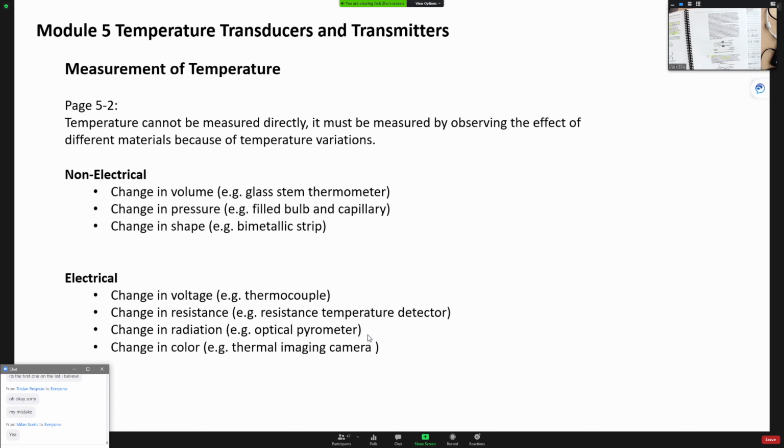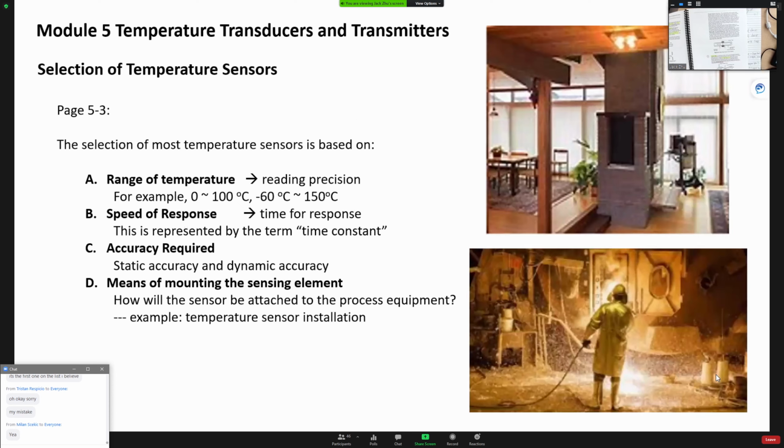The regular use is, you guys probably on some of the jobs saw those thermal imaging finders, like a gun or something. People usually use it to check the connections inside the panel or inside the big junction box to make sure you don't have overheating in those places. They will also use the thermal imaging camera to show different colors. They can use the color to identify which point is hot, which point is cool.